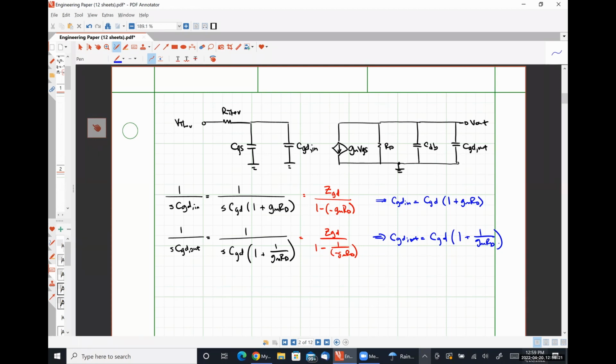All right. And so at this point, we can get to determining our transfer function, right? I need to put VGS right here because I forgot to do it earlier. So how are we going to develop our transfer function for this split up system? It's actually much easier than it was previously, right? So our input voltage V Thevenin is related to this quantity VGS using voltage division.